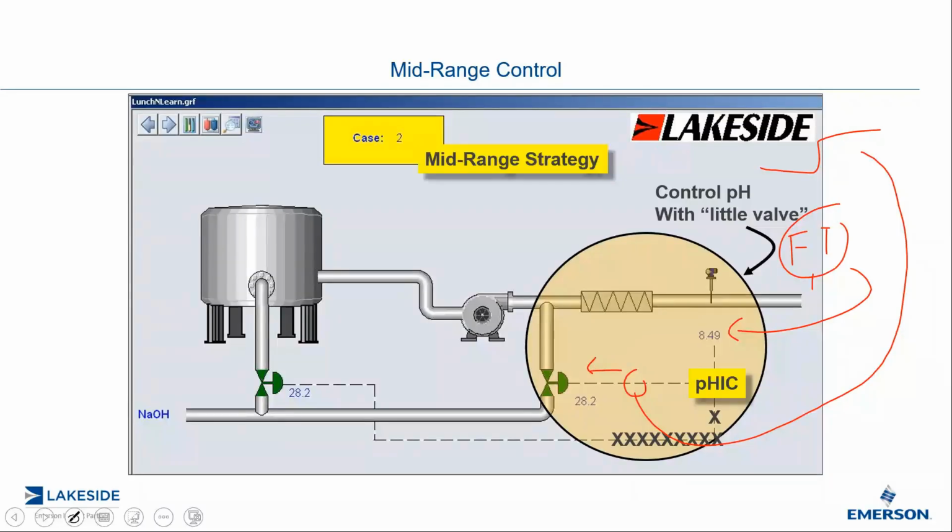And so what a decoupler does there is that it's like a double feed forward. If flow control has a problem, it will change the flow control valve, but make the equal and opposite change on the pressure control valve so that the pressure does not see any disturbance, and the opposite happens. So long answer, but the answer is the mid-range is not a decoupler.